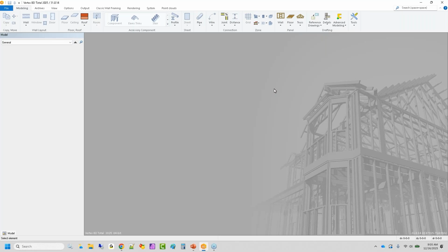So obviously, if you can save those wall types, predefine them, get them saved in your custom wall libraries, then that's going to save you the time of having to go back and forth and reselect all those changes, and it's going to help prevent all those mistakes. So we're going to go through that process of creating these custom walls, custom framing rules, and then save them either into project-specific libraries or your custom library where they'll be available for all the projects that you're working on.